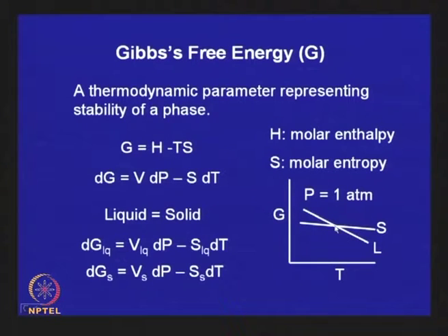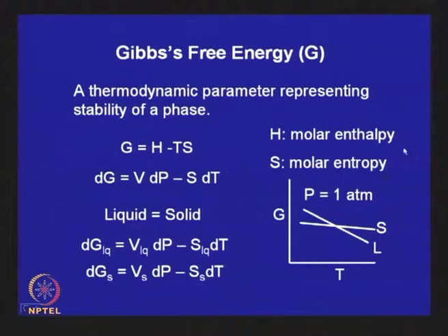so essentially what is happening is, does solidification begin immediately when it comes below the freezing point? At freezing point this is 0, but what happens when a solid nucleus forms? A new surface is created, and to create this surface you have to apply a certain amount of energy. Where does it come from? What is the driving force? So, that means that energy has to be supplied, and this can come from this chemical potential, and this is possible only if you go down, I mean